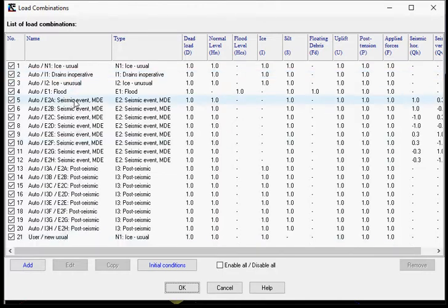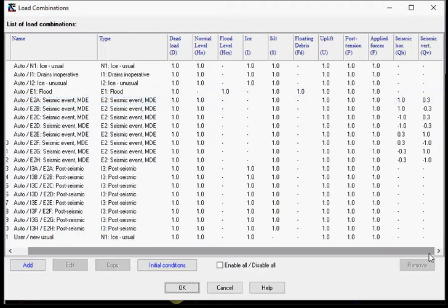For the seismic cases, since we have two directions, the horizontal and the vertical direction, and we have a combination of both, sometimes we put full in one direction and 30% in the other direction. In this case, for the horizontal seismic would be upstream, downstream, and the 30% of the vertical seismic. And we can as well play with the direction of the seismic. So all these possibilities end up having 8 seismic events. And these seismic events will produce 8 post-seismic events.